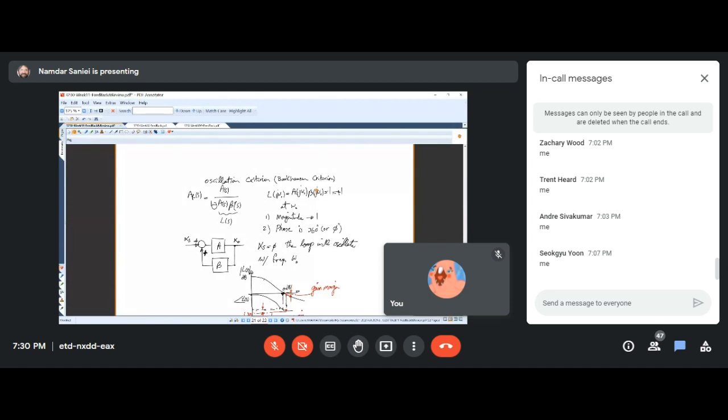Now, if the sample is exactly reciprocal of the amplification, then the loop gain, and this is the loop gain that we are talking about, L, becomes 1. And for the frequency at which this has happened, the gain is 1, and the phase has turned 360 degrees. That's the frequency at which you can expect the oscillation.